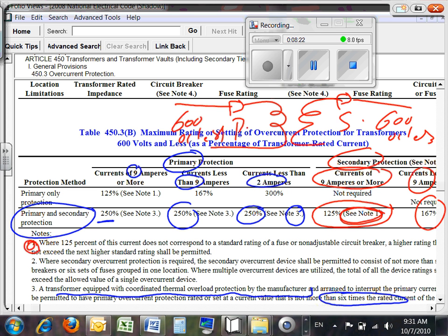Some of these guys have sensors. Some bigger transformers have sensors in the gut of the transformer that interface with the relay, and the relay can trip the circuit breaker in case of an overload or temperature rise in the winding of a transformer. If you have a 20 meg transformer, you would hope that you protect that boy with everything that you can. You would hope that a fuse like this is not the only protection that you have for this 20 meg transformer. It's a huge piece of equipment, a huge investment.